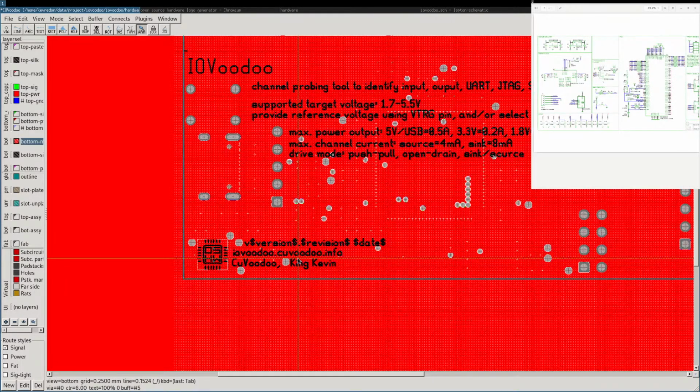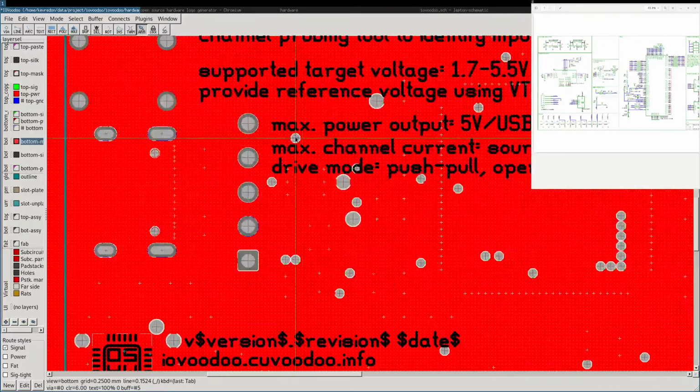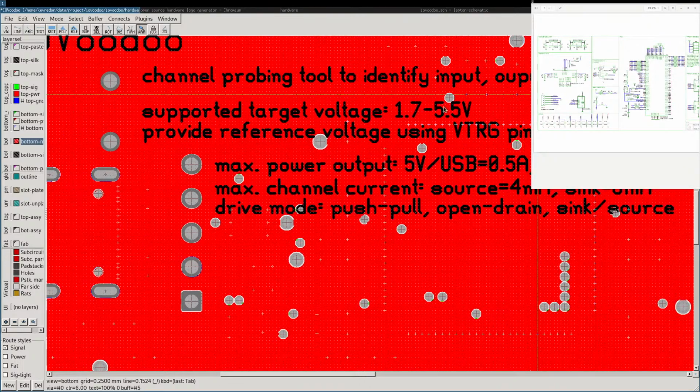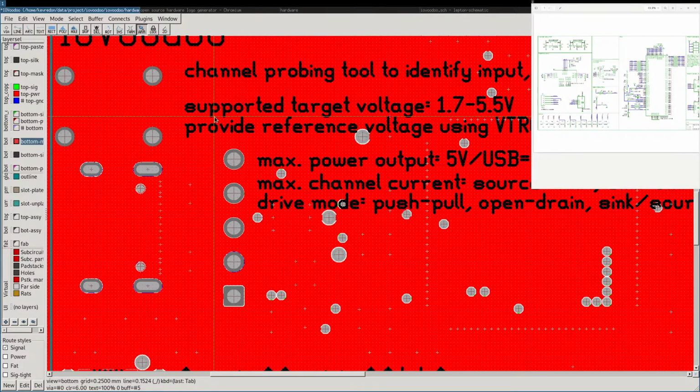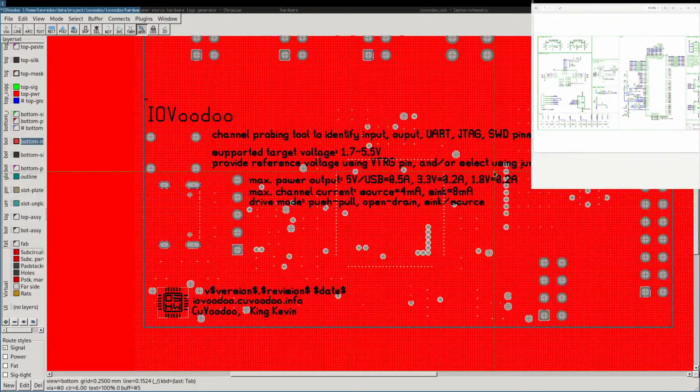That's okay. And for example, what I did pay attention here, you see there's no text over the holes, almost no. So there's just a tiny bit. This is because they are open. If they would be tented, I would have no issue writing on top of here. Here I did put a bit of attention because they are open, so there is no solder mask, and without solder mask it's hard to have silk screen really printed on it. And generally they are here.